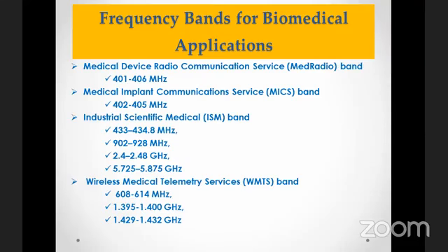The frequency bands which are used in biomedical applications are of 4 categories. First category is MED radio, medical device radio communication service band, which is 401 to 406 megahertz. Then MICS band, medical implant communications service band, 402 to 405 megahertz.